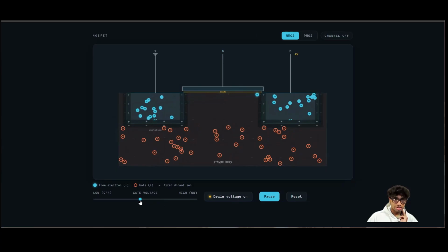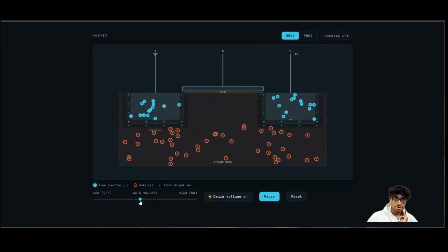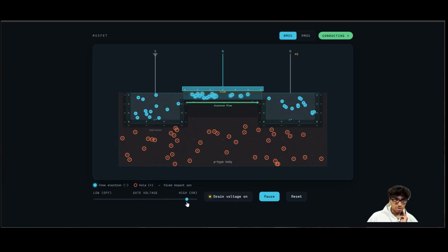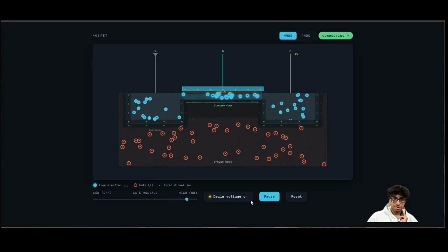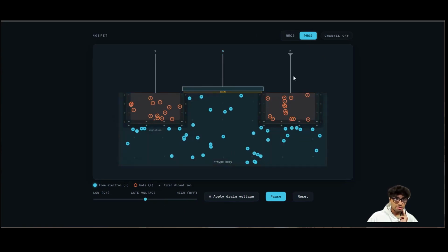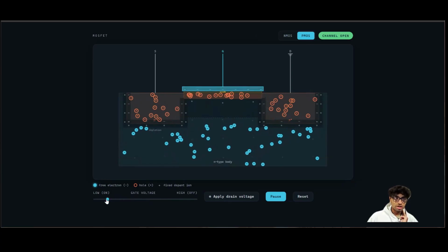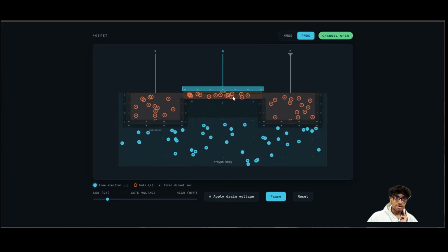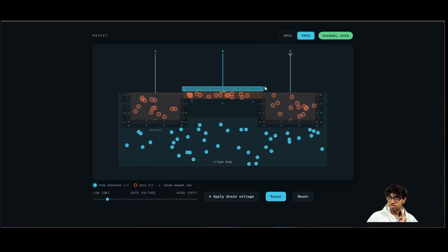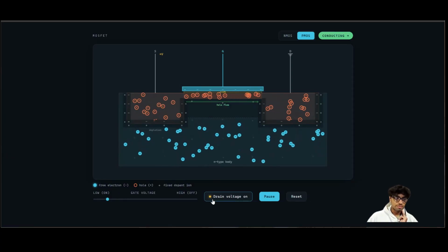If I don't apply that voltage at the gate, then the gate is closed, there is no channel, and current can't flow. If I do apply that voltage to the gate, then the gate is open, and current can flow. Now for a PMOS, you have to do the opposite thing. You have to go to a low gate voltage. A low gate voltage pushes away the electrons in the N-type body and creates a channel for the P-type positive charges, so that when I apply a voltage, current can flow.